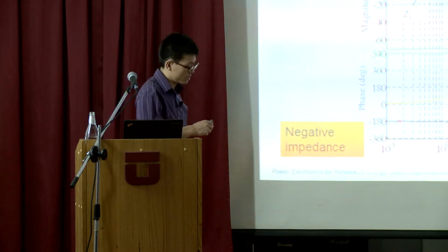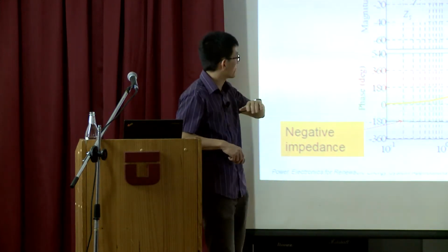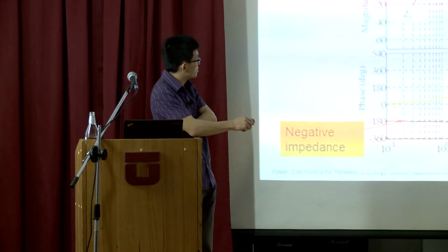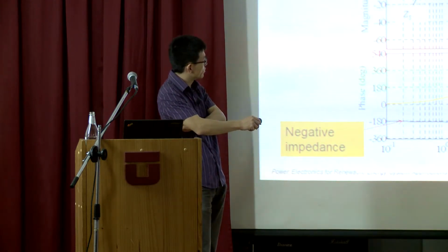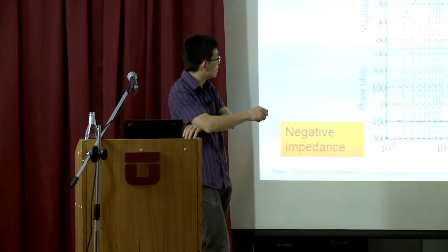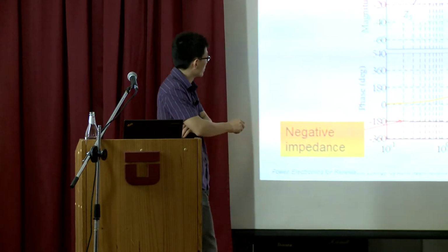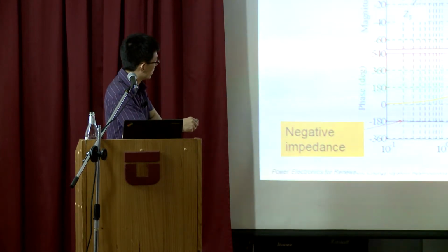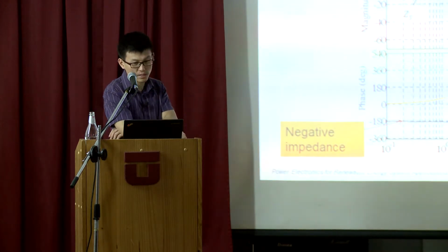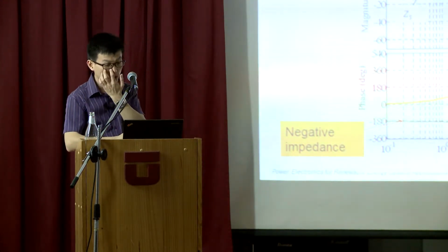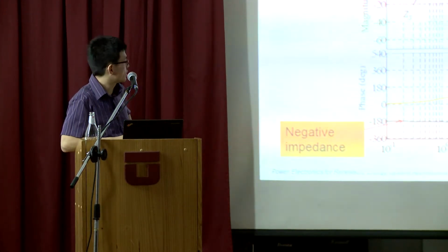So you look at the source impedance when I have multiple sources connected together. With n equal to 1 and then when I increase it, we find in this area they are shifted inwards, but there's not a big difference here. When the frequency is very low, you might see a little bit of difference. It's beneficial to the stability, but not that much.